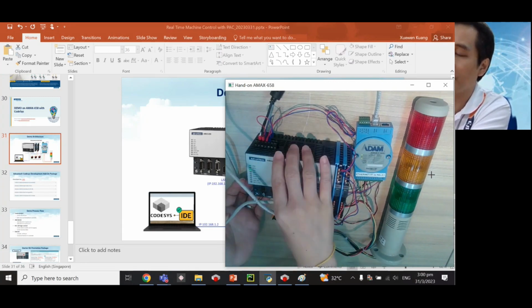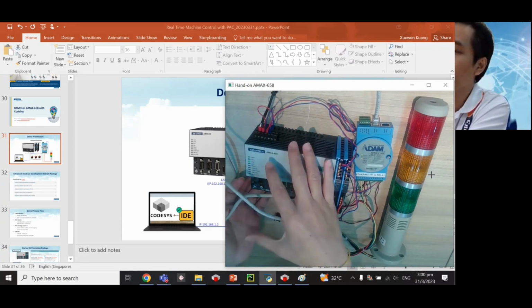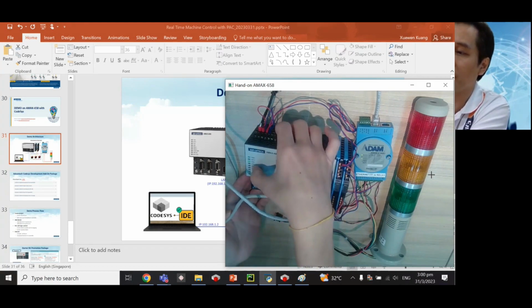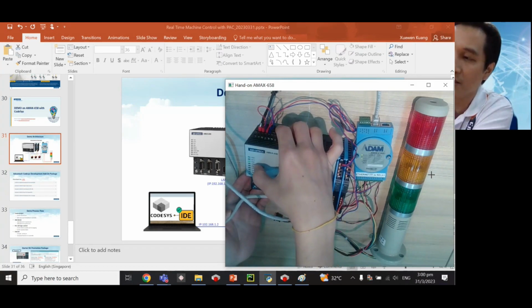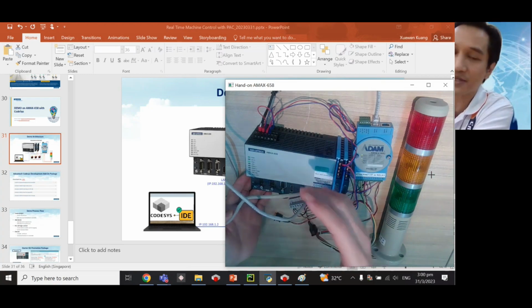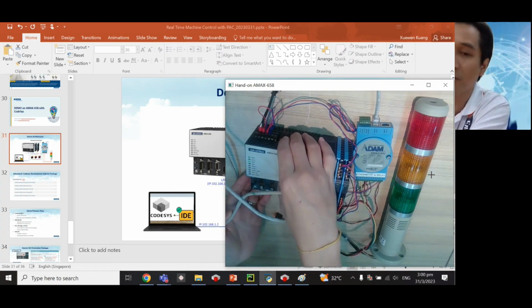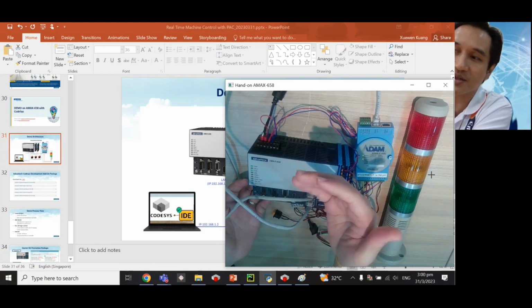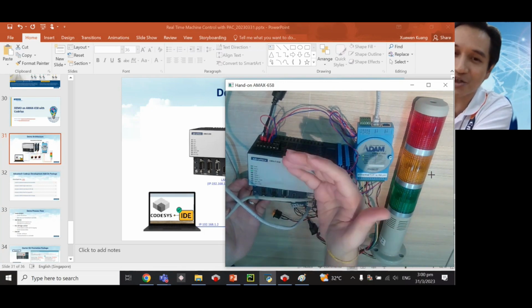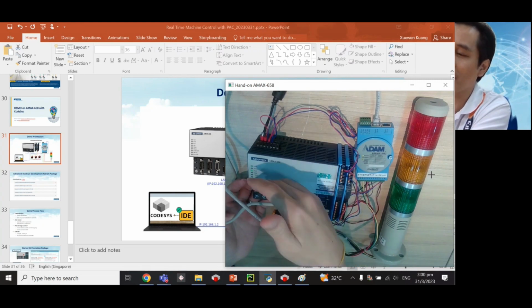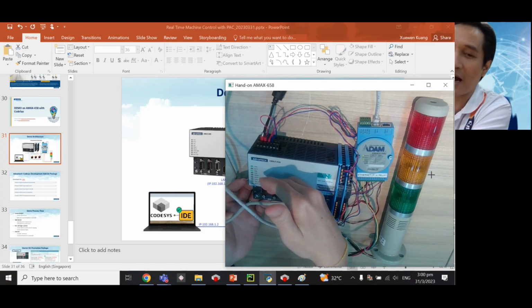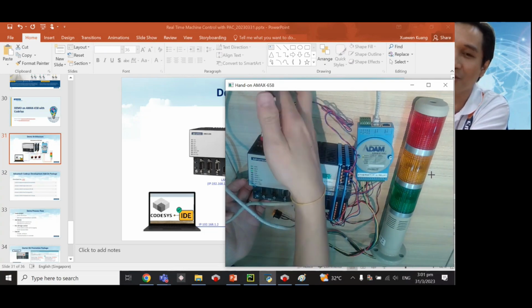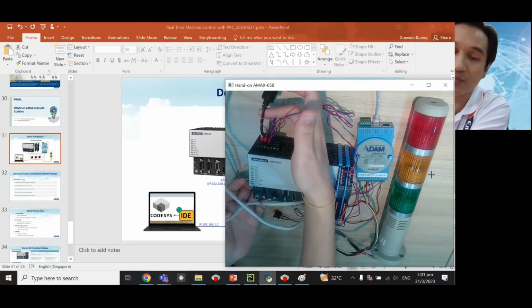Sometimes if the internal CPU is overheating, this LED will be triggered. It will say over temperature. We do have another error LED for voltage. What does the voltage error mean? The first time I tested this hardware, my power supply was 19 volt. I didn't check the data sheet and just supplied power, and this error LED turned on. After I found out the issue, it was because I was not using 24 volt power. Our power supply requires 24 volt power.